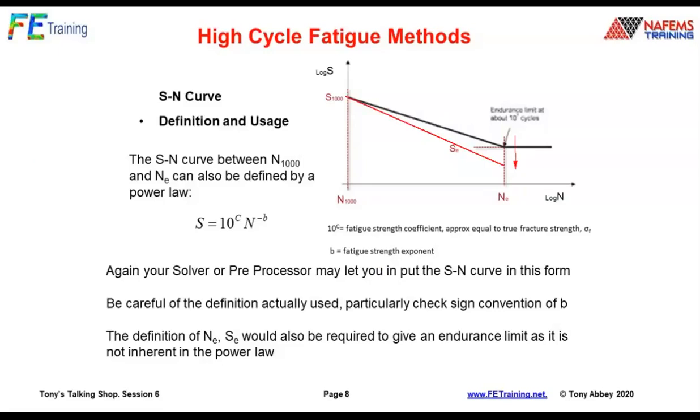Notice that very often I don't mess around very much with this area up in here, because I'm assuming that's governed by yield failure. In other words, like a static failure. This is more for fatigue prone. So again, that's another little clue. And modifiers, which are very, very important, are going to be typically applied at that end. And those modifiers can be very important.